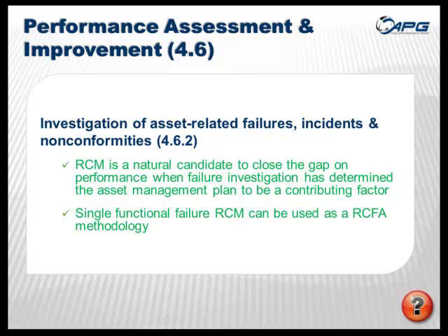It has occurred in the past where RCM as a tool has been used for root cause failure analysis techniques. When someone comes out in the morning to start their car, and they turn the key and the car doesn't start, you know instantly what the functional failure is. Car won't start. At that point in time, it's unlikely, unless you have other information readily available, that you can identify the individual failure modes or single failure mode that resulted in that. But you always know the functional failure.